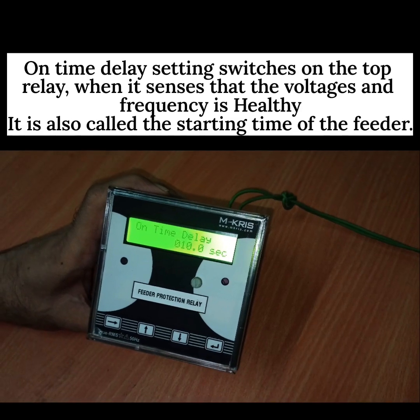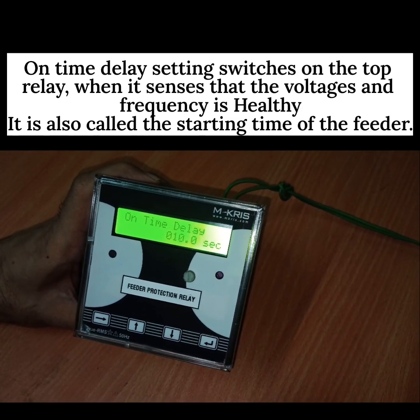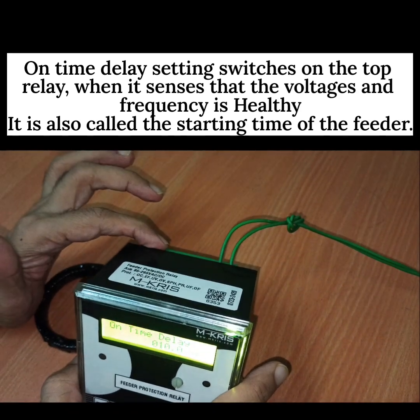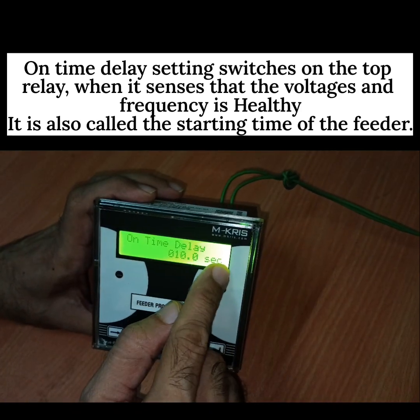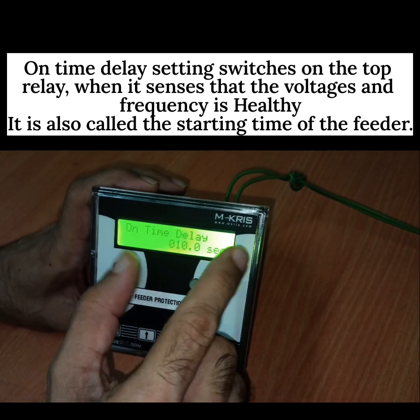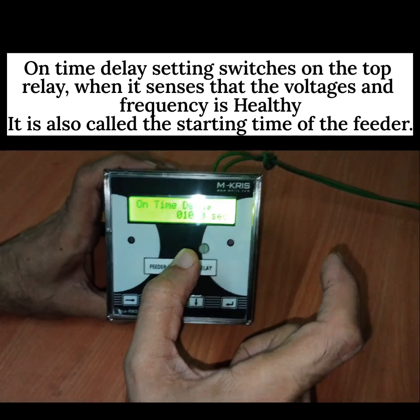On time delay represents the time, let's say when the relay senses that voltages are healthy and frequency is healthy, it switches on the top relay. And when this relay is energized, this is the on time delay, which can also be called the starting time of the motor or the starting time of the feeder. So during this time, the protections will be disabled.